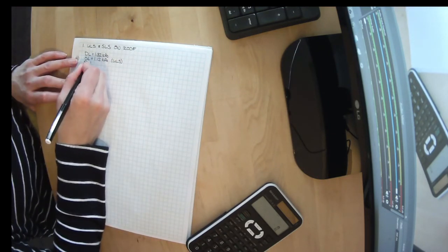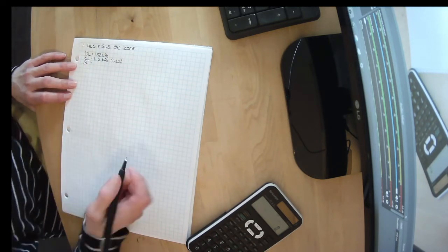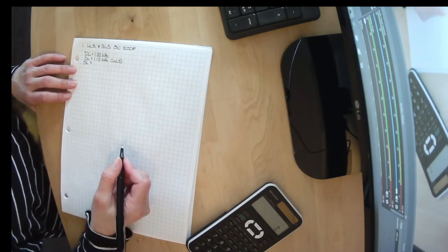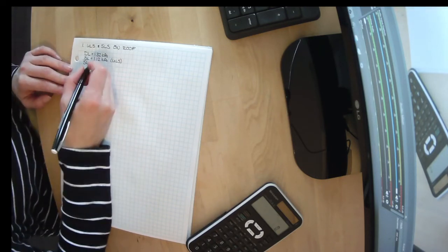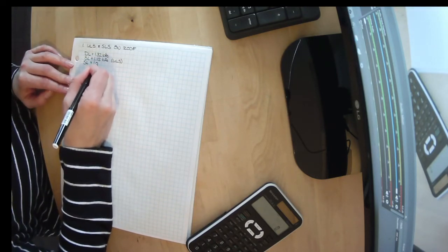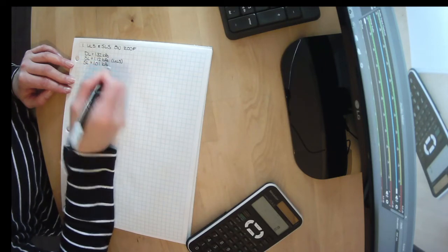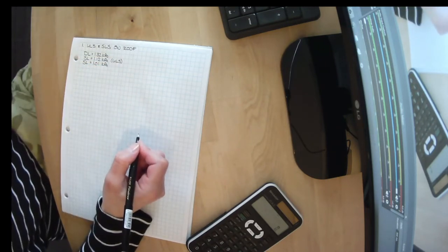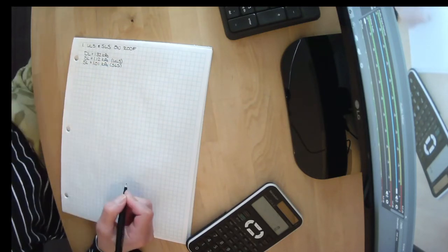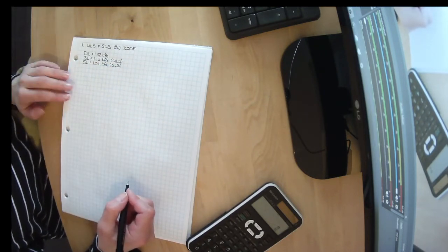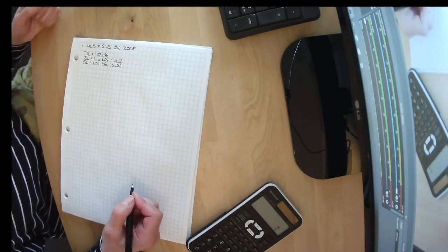We also know that if we are talking about serviceability criteria, that importance factor isn't 1, it's 0.9. And we calculated that we had a serviceability snow load case of 1.01 kPa. Essentially, it's our snow load times 0.9.